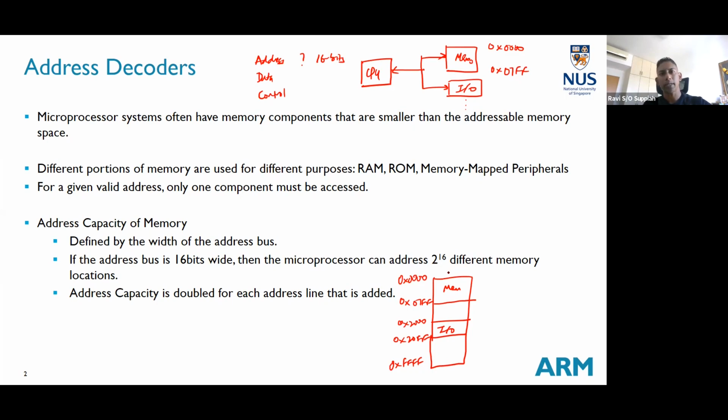Okay, but if you look in the header files, you will see that all the registers are mapped to specific addresses. When I wanted to configure port A, the data direction register, or set a bit to 1 or 0, or configure the UART at a certain speed, all of those are registers which are mapped to specific addresses. This mapping is already done for us by the team that designed that board. But if you want to do it on your own, then you need to map all these subsystems and their addresses to the address range that the processor has. So that is the whole idea over here.